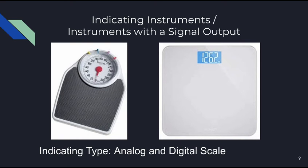The final way in which instruments can be divided is between those that merely give an audio or visual indication of the magnitude of the physical quantity being measured, and those that give an output in the form of a measurement signal whose magnitude is proportional to the measured quantity. The class of indicating instruments normally includes all null-type instruments and most passive ones. Indicators can also be further divided into those that have an analog output and those that have a digital display. A common analog indicator is the liquid in-glass thermometer.